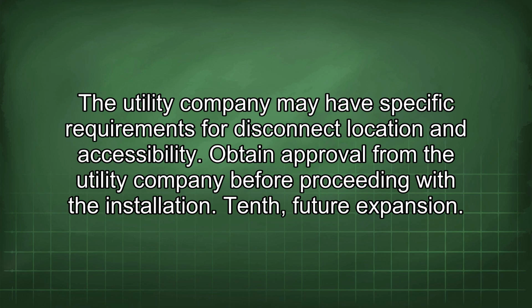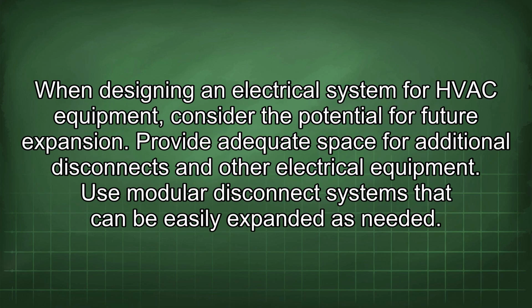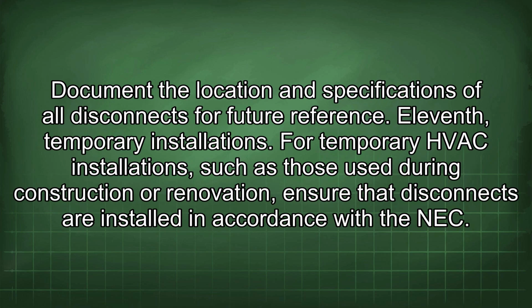10th, future expansion. When designing an electrical system for HVAC equipment, consider the potential for future expansion. Provide adequate space for additional disconnects and other electrical equipment. Use modular disconnect systems that can be easily expanded as needed. Document the location and specifications of all disconnects for future reference.